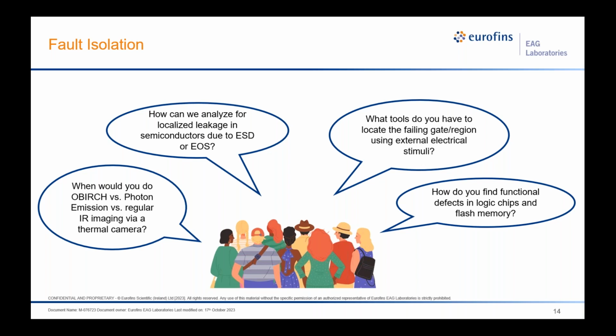In terms of nanoprobing, you have several techniques. You can use EBIC, EBAC, or EBIRCH. So it is a lot more involved and requires a service lab to work closely with the client on this type of problem, functional failures.